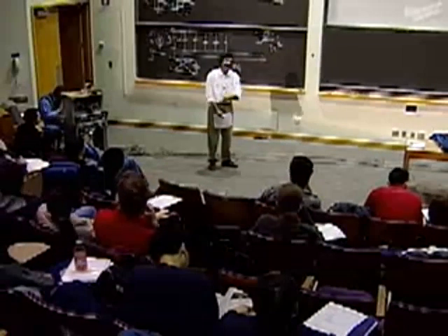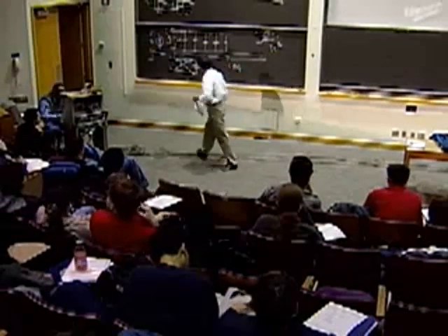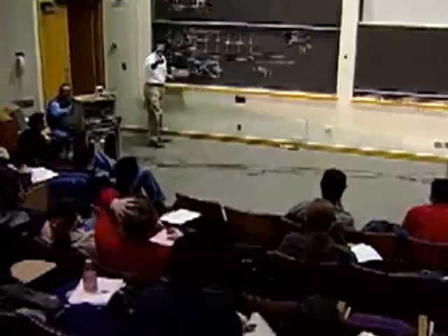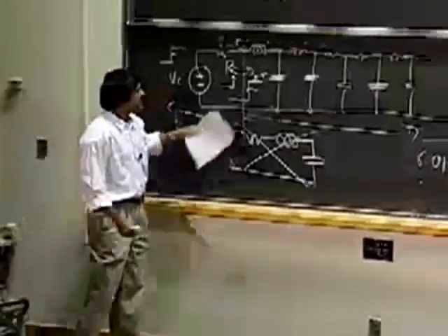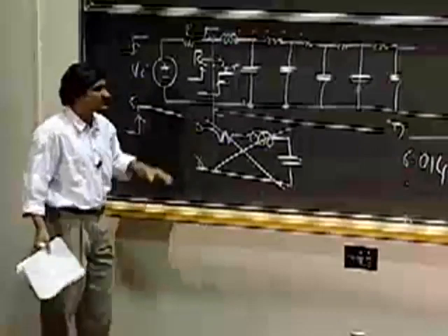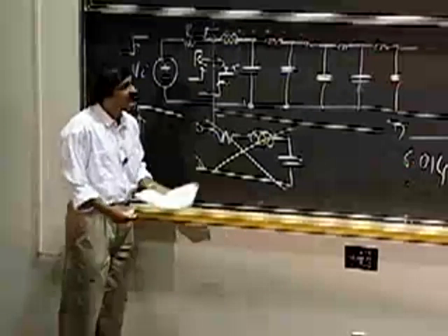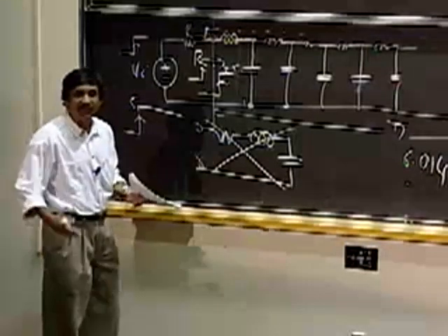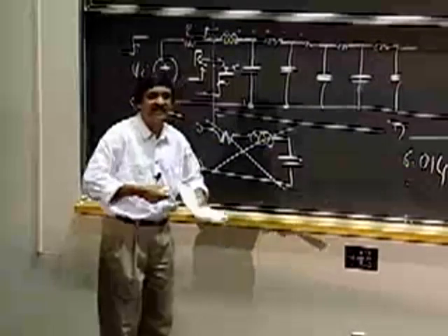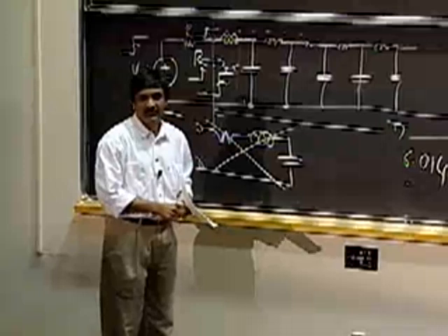Yes? Clock. So what I can do is, just as was pointed out, that I leverage my abstraction by changing my VOH and VIH thresholds. So that'll work. The alternative thing is to use a clock. A clock is a distinguished signal that I send around in my digital circuit. Okay?